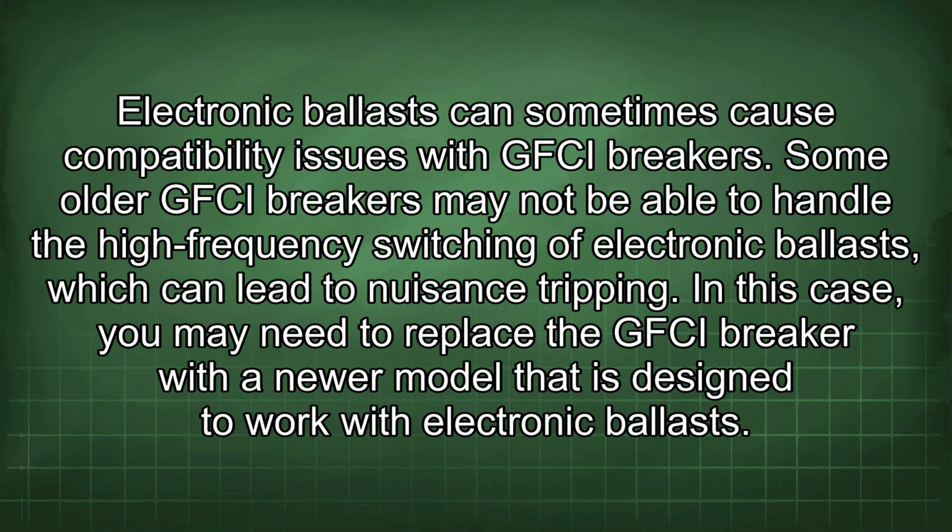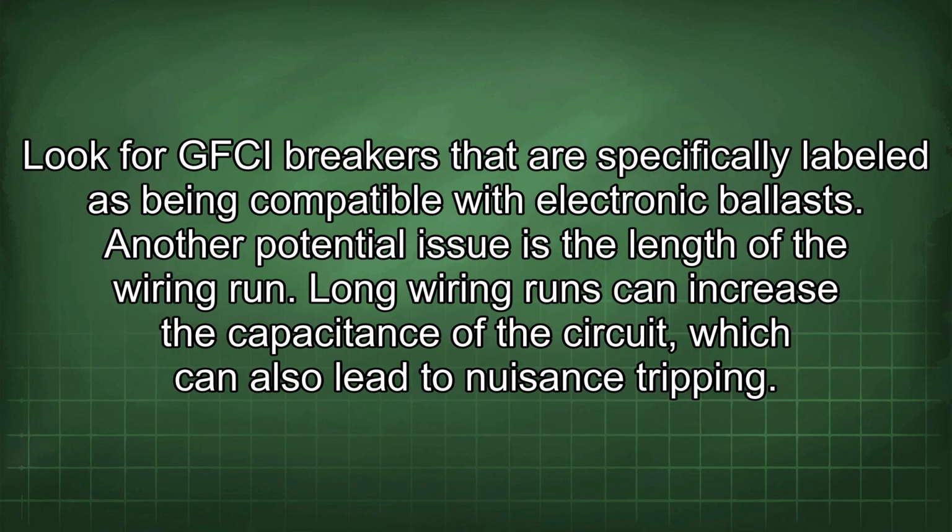Electronic ballasts can sometimes cause compatibility issues with GFCI breakers. Some older GFCI breakers may not be able to handle the high-frequency switching of electronic ballasts, which can lead to nuisance tripping. In this case, you may need to replace the GFCI breaker with a newer model that is designed to work with electronic ballasts. Look for GFCI breakers that are specifically labeled as being compatible with electronic ballasts.